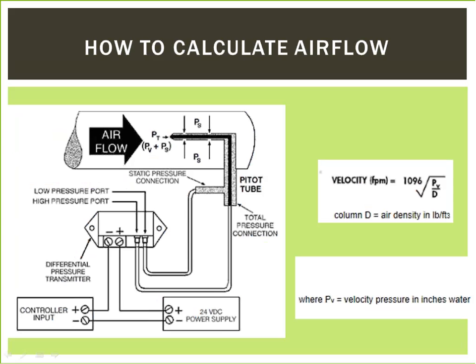Building automation systems are often required to measure the actual airflow in air handling systems. Although there are many ways to measure airflow, the two most commonly used with BAS systems are the hot wire anemometer and various devices which measure the velocity pressure of the air. Once the velocity pressure is known, the BAS is then able to calculate airflow. Each method has its own advantages as well as disadvantages.